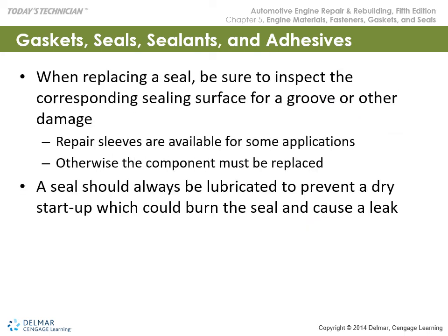Okay, they talk about repair sleeves being available for certain high-valued applications. There are also some machine shops that are able to help if you have a high-valued crankshaft or camshaft and the nose has a groove in it, or even a damaged journal.